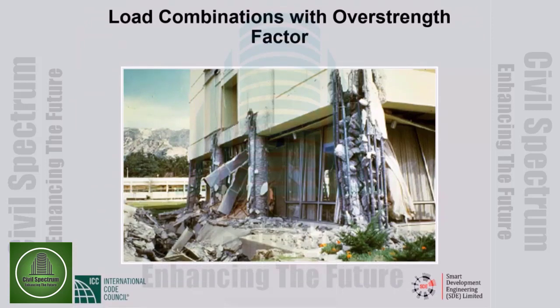This is a by now famous picture. This was the Olive View Memorial Hospital after the 1971 San Fernando earthquake. You see the bottom story has columns, and then the shear walls start. Okay? Those columns, back in those days when there was no difference between a California column and a Chicago column, have plenty of longitudinal reinforcement, hardly any transverse reinforcement.